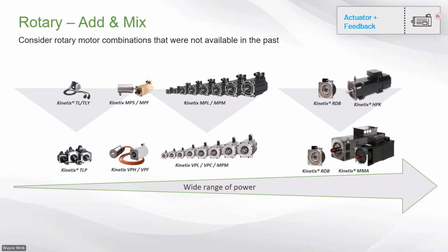Old motors can survive, in some cases, for decades. I'm sure we've all seen them, if they're selected carefully and if they're not abused in the application. And they can often, but not always, be reused when you're doing a drive modernization. But do consider motor combinations that were not available in the past, such as the rotary motors shown here, like the TLP motors, single cable Kinetix VP series servos, or the option-packed Kinetix MMA motors.